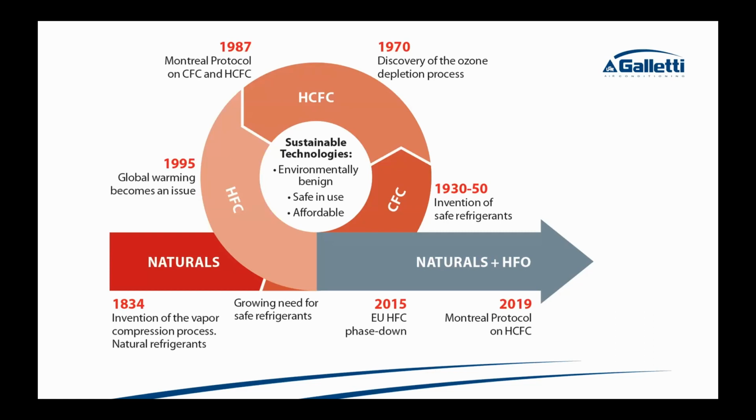which I skipped. So the current charge limit in the United States for R290, which is probably going to be the major refrigerant, is probably the equivalent of 2 Bic lighters. It's like 150 grams. It's not going to do much. They're looking to increase the charge limit to 4,900 grams, like half of your propane tank on your grill. And they could probably break it up even by circuits. But we're a bit behind Europe in that sense.